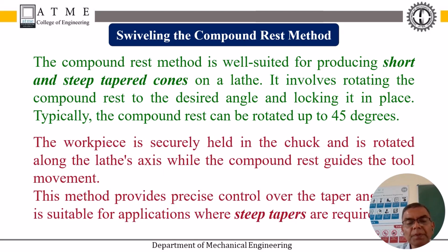Here the workpiece is rigidly held in the chuck and rotated along the lathe axis, while the compound rest guides the tool movement. Thereby the taper surface can be generated. This method provides precise control over the taper angle and is suitable for applications where a steeper taper, that is a steeper angle, is required.